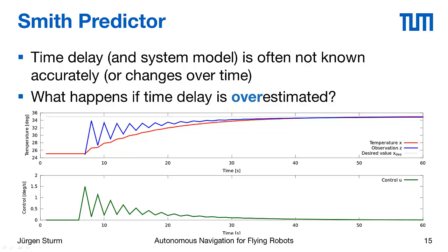So it will greatly reduce the controls in the next time step because it thinks that we're already going too fast, and then it would project that into the future and realize that it's actually too slow, and so it would go back and forth and oscillate. As you can see, this is clearly not optimal, and it also leads to large changes in the controls, which is not what we want because this costs a lot of energy.